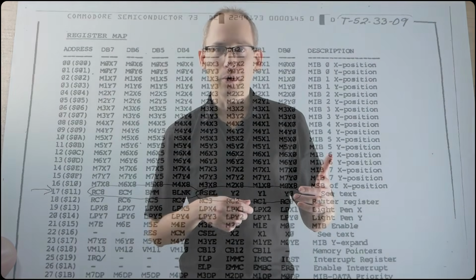But invalid video modes are not the answer this time, because although they would address the first problem, which is to perform the necessary register updates using only A, X, and Y, we still have the second problem, which is that the sprites aren't wide enough to cover all the splits. But there is a way. We can use the upper bits to select a video mode called Extended Character Mode, ECM.